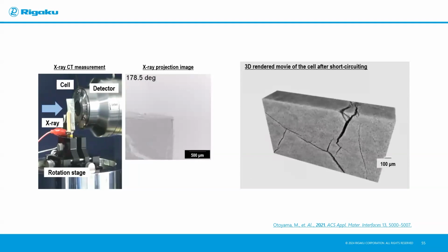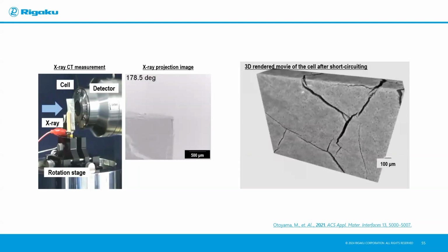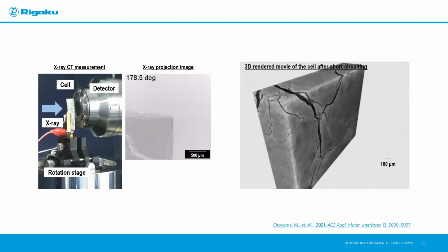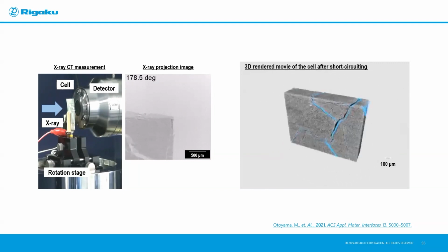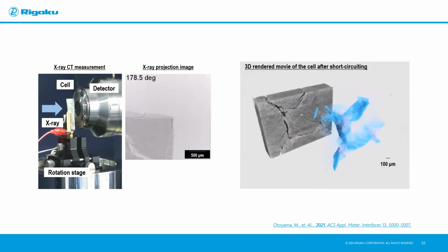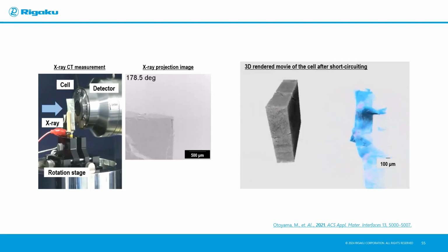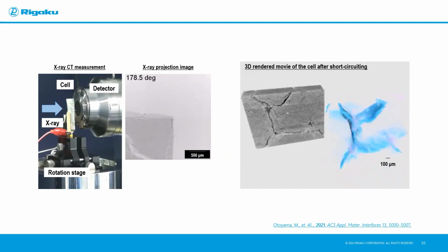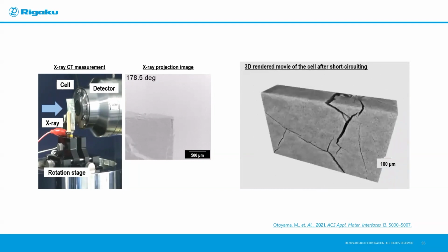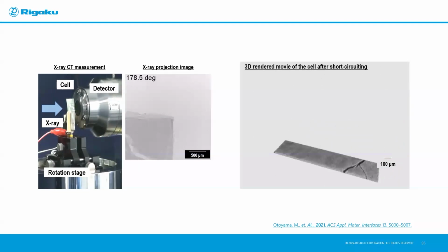And they took this data along with data from XRD to characterize different areas and SEM to understand what exactly was happening structurally inside. And in this paper, they explained that there are chemical changes identified by XRD within the battery that led to lithium cluster formation. And those clusters caused concentrated stress and ultimately the formation of cracks. And over time, the cracks cause short circuiting of the battery and eventually a failure.